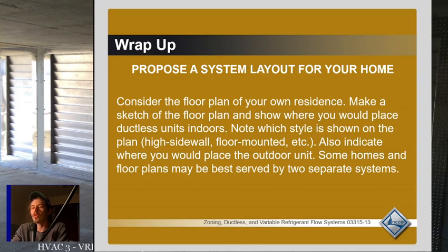And in general, you should err on the side of undersizing a system, not oversizing a system. If you're undersizing a little bit, you need to explain to the customer, hey, the system should be like 13,500 BTUs, but we're going to put in 12,000 BTUs, which means on a very hot day you may not be able to get it under 74 degrees or so, but usually as long as you're controlling humidity, that's relatively comfortable. You will be more comfortable doing that than oversizing this system by another quarter or half a ton, and it'll overall work better.